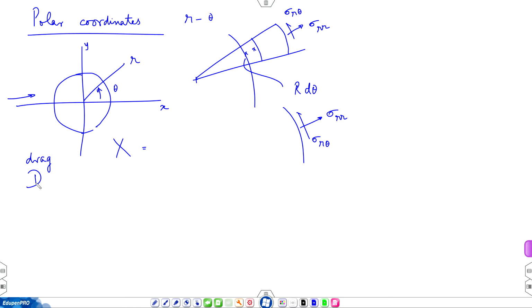Now we are talking about calculation of those drag coefficients from the local description of the flow field. How will I get the local description of the flow field? That is by solving the local form of the mass and momentum equations. Those equations look somewhat complicated, so we will deal with them as we go along, but for the time being let us say you know